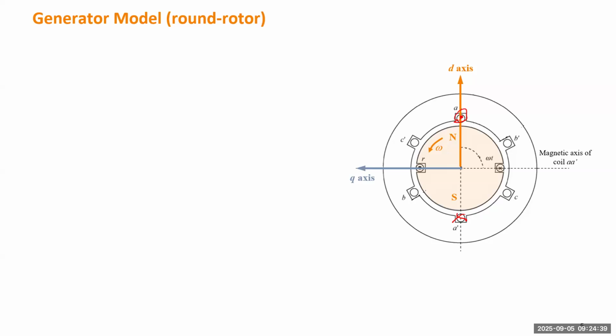So next we want to determine the initial time, which is important because in section 2 we use the cosine function as the basic function to formulate AC current and voltage. So we still stay with the cosine function because we need to write down the expression for how the flux linkage changes. Under the static state condition, the field current in the rotor will be constant. It will generate this constant magnetic field, which is like a permanent magnet revolving inside.